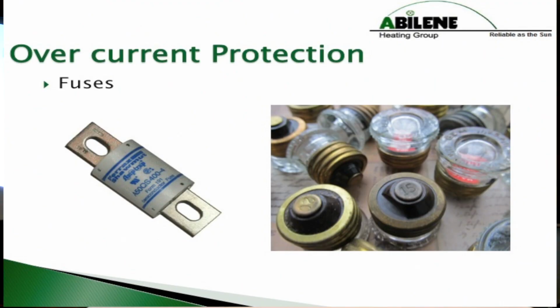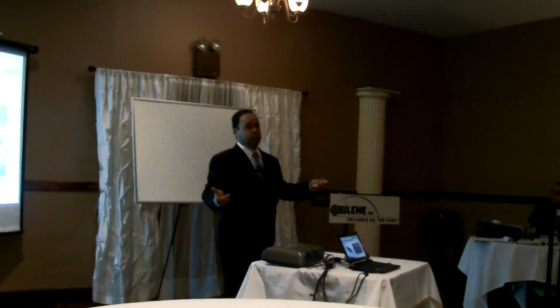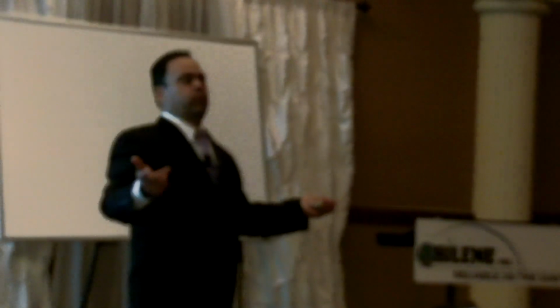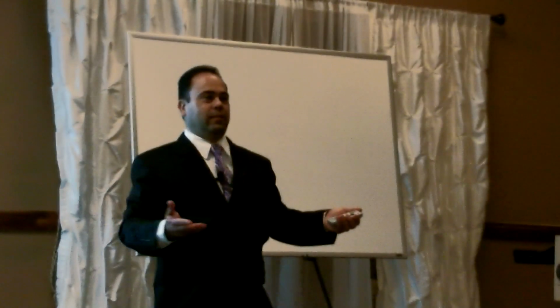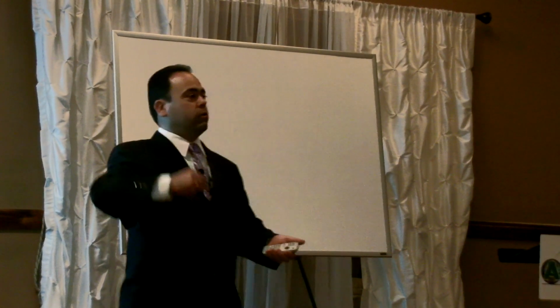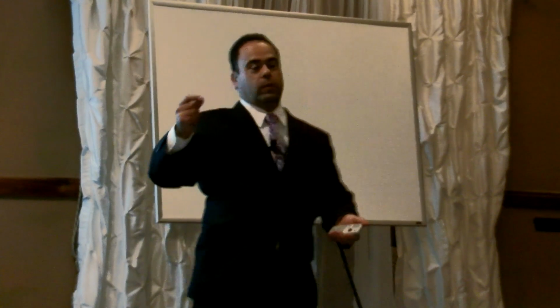Overcurrent protection, we talked about fuses. This is a silver sand fuse, okay? Difference between circuit breakers and fuses. Anybody? A fuse is one time. That's it. It blows, it's done. You're throwing it out and you're getting another one. A circuit breaker is a resettable device, okay?